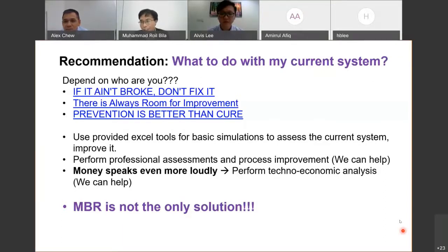Well, this is the advantage of MBR. You cannot do it for activated sludge, but yes, you can do it for MBR because we don't care about the state of the sludge. As long as it is a microorganism, it will be separated by the membrane. So when you have this kind of problem, it's time for you to shift from the normal activated sludge to MBR, because fixing this problem in activated sludge is a headache.